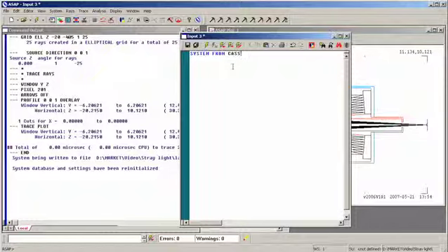I now want to add scatter properties to the object of interest. Here we go. The object of interest is called conbaff.inside, meaning conical baffle, interior surface. I merely issue the command object conbaff.inside, which tells ASAP this is the object that I want to modify. I'm going to enter a very simple model.